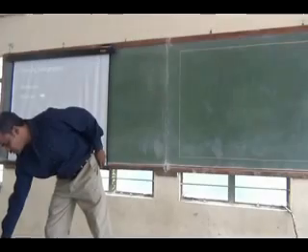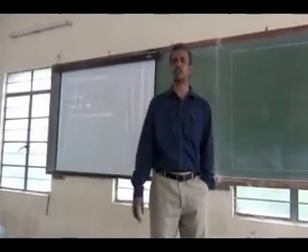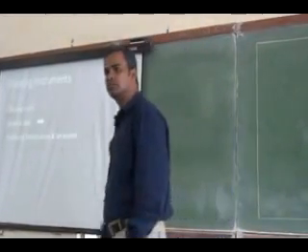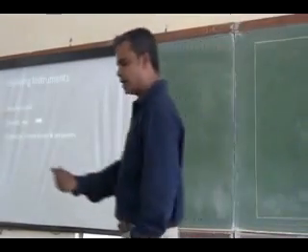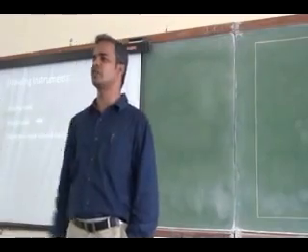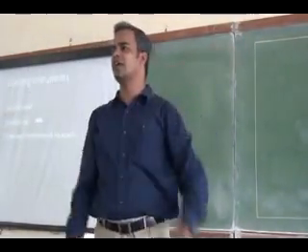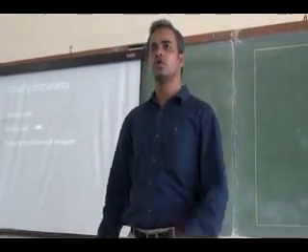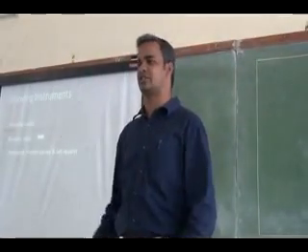So the next instrument, you have protractor, French curves and set squares with you. Right. So what is the use of protractor? You know, I can use it angular measurements I can take it. Right. You have set squares, two set squares with you. So one set square is exactly 45 degree. Okay. 45 degree set square you have. So 45 degree line, if you want to draw it, I can use the 45 degree set square.